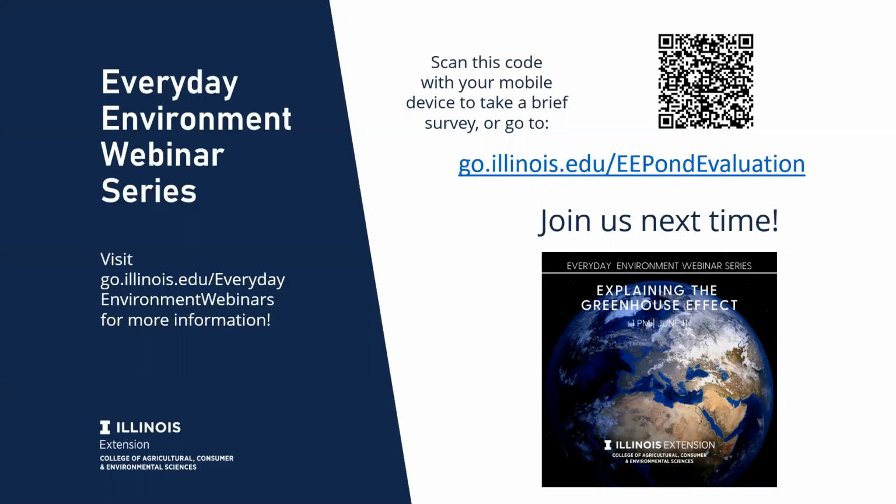Right. Okay, great. We had a question about if all sides of the pond have to have a 5-foot drop, and if not, what percent would you suggest having that drop? You don't have to have all of it. The more of it, and especially if you start from the dam working back towards where your water source coming in is at, the more of that you can keep somewhere close to a 5-foot drop, or getting it down to that 5 foot pretty quickly, the less of a weed problem you're going to have around it.